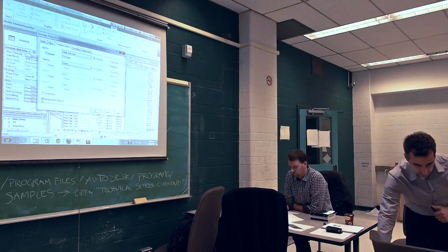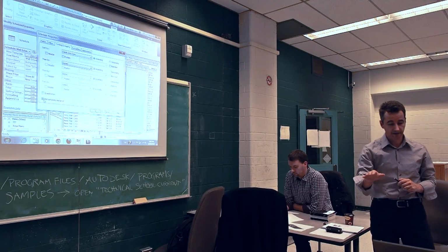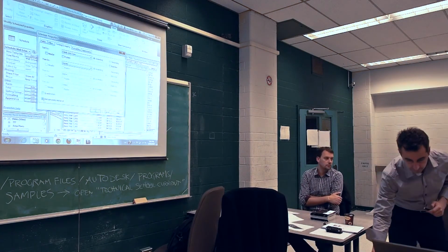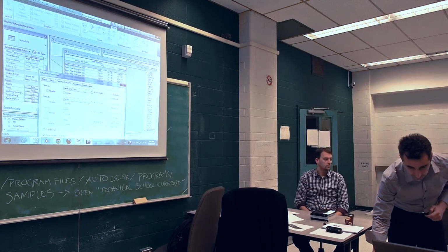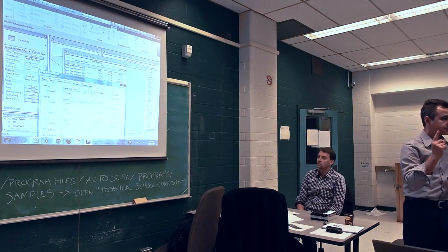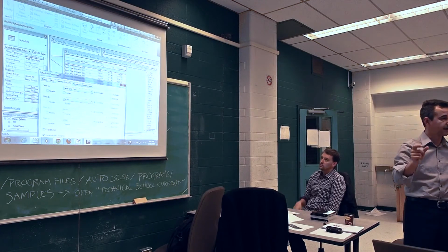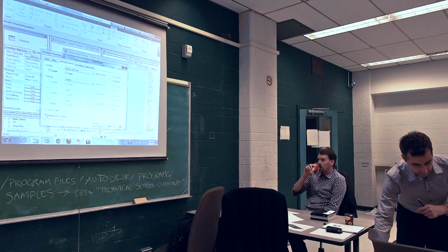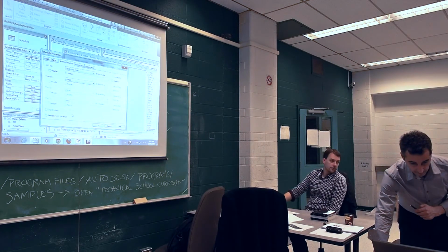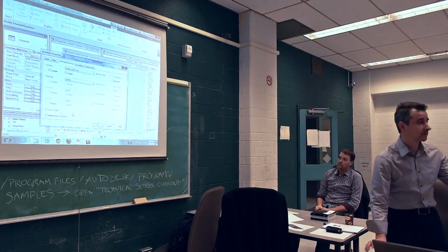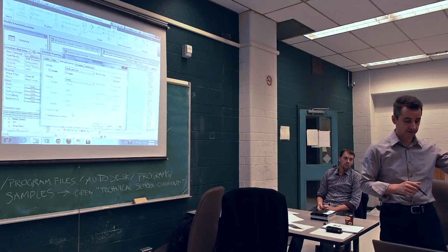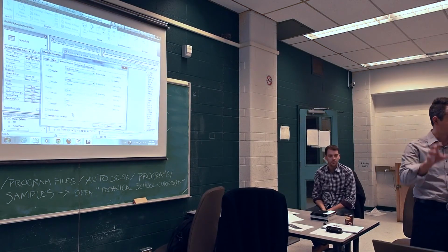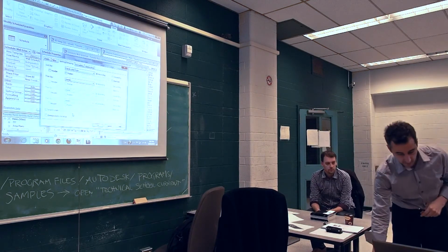Yeah? We said we don't want every instance itemized. You only want bulkhead 300 once, and then the cost per unit, and then the area and the total cost. So we want to disable this itemized in every instance. Right? Let's see what happens. Because I promise you, going through this exercise yourselves, you'll have to do this step by step so you understand what the differences will be when you create the schedule.